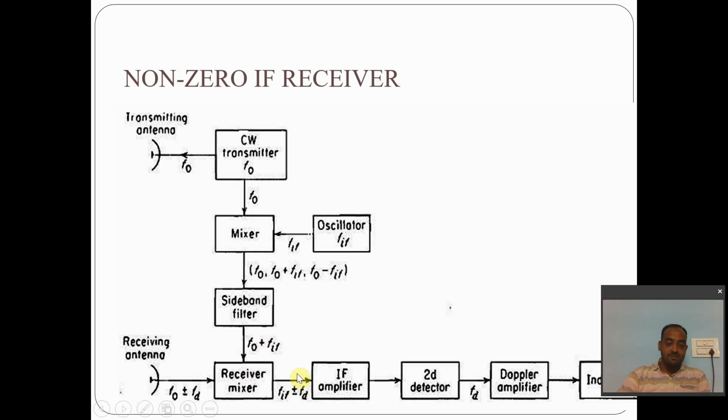In the previous case, the operating frequency was Fd, which is normally very low, of the order of kilohertz. Low frequency produces the flicker effect, called flicker noise, so the previous system suffers from flicker noise. That is the reason we have intentionally inserted a medium or high frequency, FIF, which will not let the system suffer from the flicker noise, as in the earlier case.